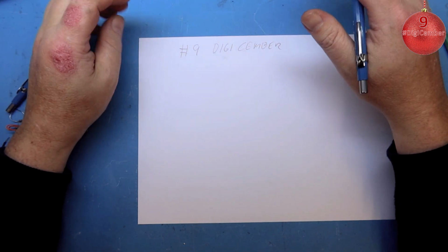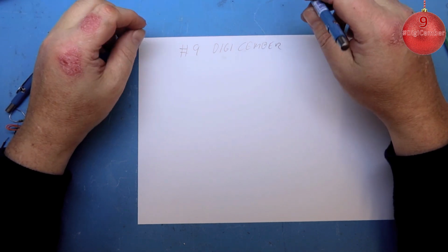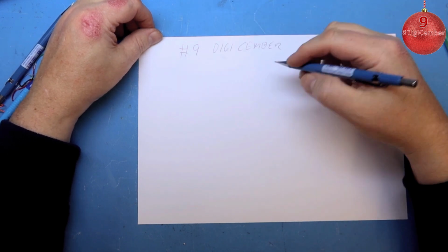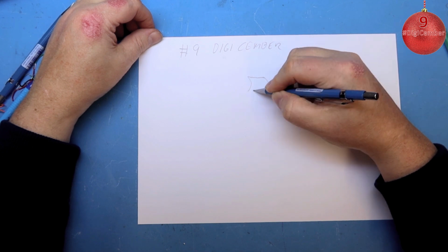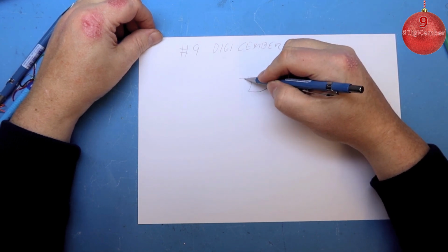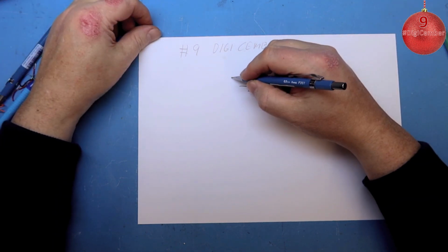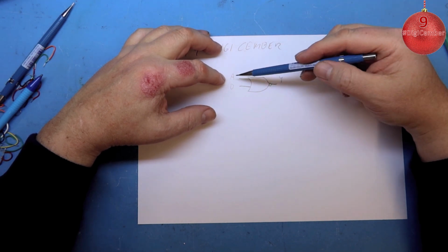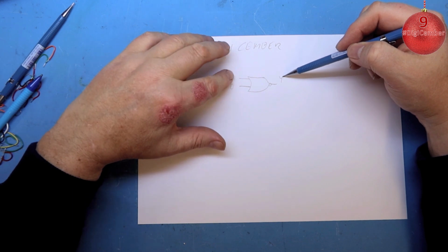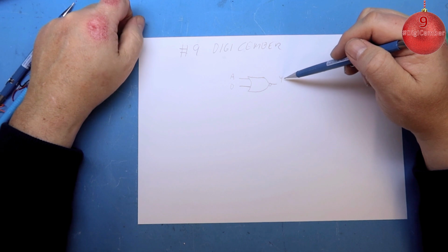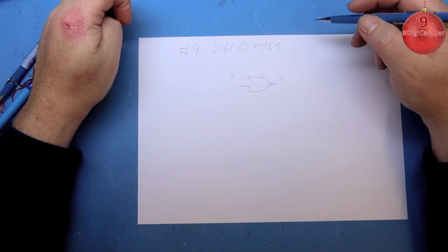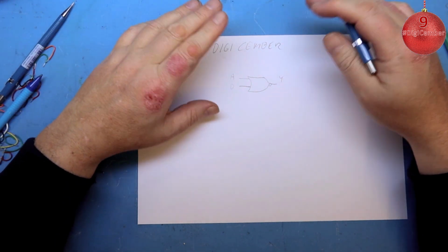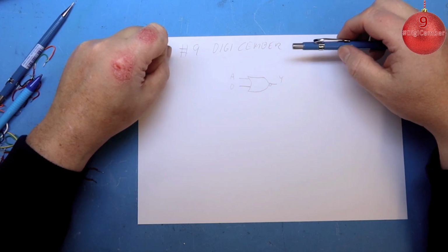Up until now we have talked about gates and logic, and combinatoric logic is the common term for this. What I mean by that is that if you take an ordinary gate, let's say we start with an OR gate, we are going to need that later on. If you just take a gate like this, and something happens on the output, it happens immediately. When we take away the signal or the pattern that we have here, it changes immediately and nothing is stored. There is no trace that we have done something on this logic chip, except if we burn it, of course. Normally it's a momentary value. It's what happens in the moment, and there's no storage.